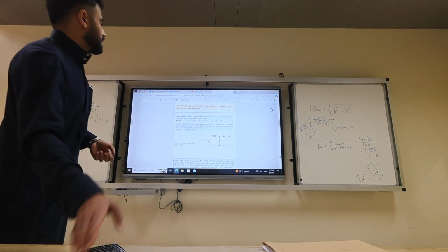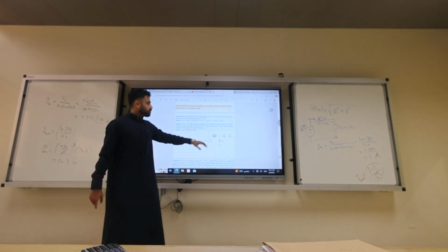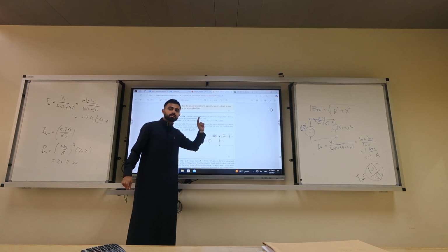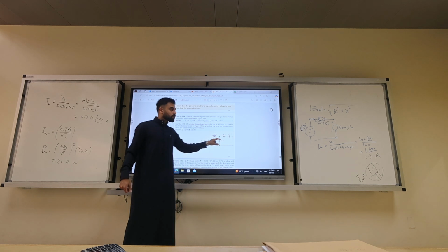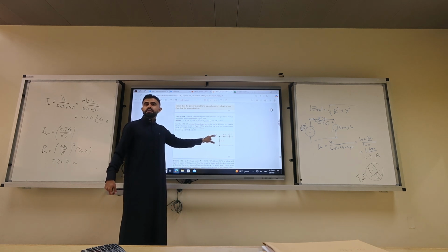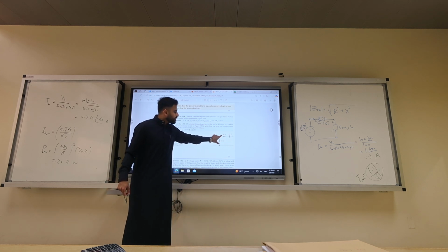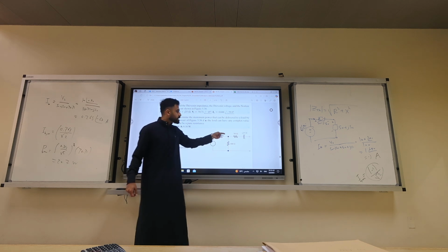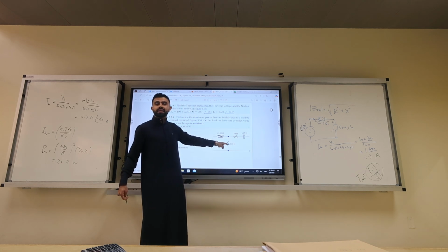What's the fastest way? Remember what I told you: if you connect R Thévenin, you see this resistance. But for V Thévenin, there is no current flowing into the open circuit. So can we use VDR? To calculate V Thévenin, it's equivalent to the voltage drop across the 100 ohm resistor, because there is no current flowing here. Now we use VDR, question 1 in the test.